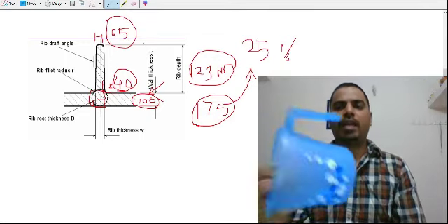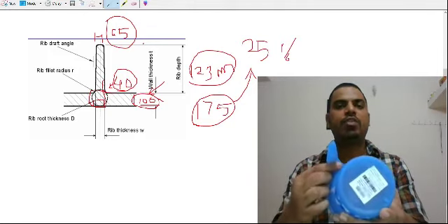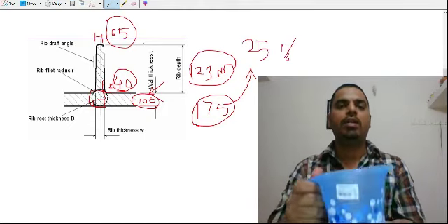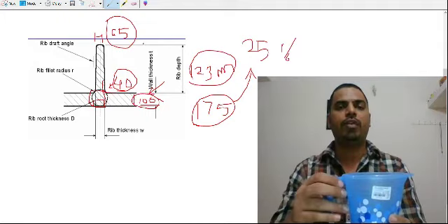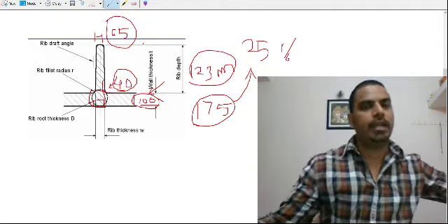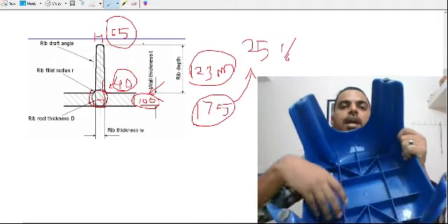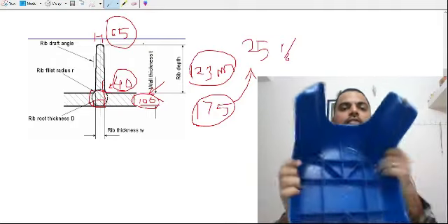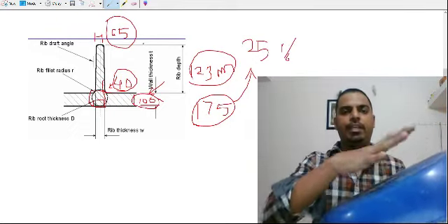An actual example: there is a rib provided at this location in order to strengthen the plastic part at this location, because stress concentration is happening here because of the loading condition. Also, in the case of this tool, ribs are provided in groups in order to increase the strength of the plastic part, because the loading condition will be in this direction.